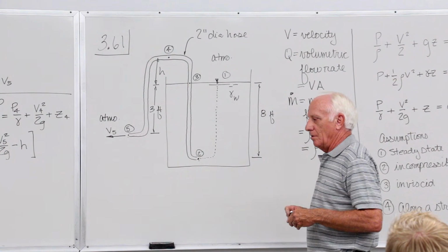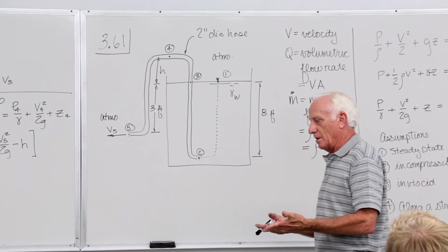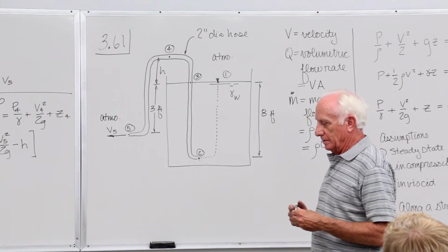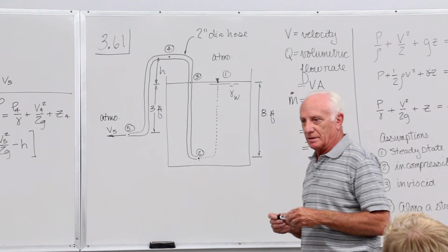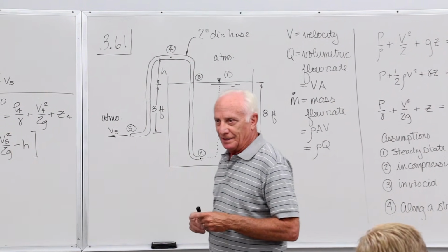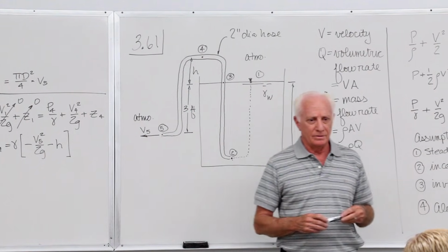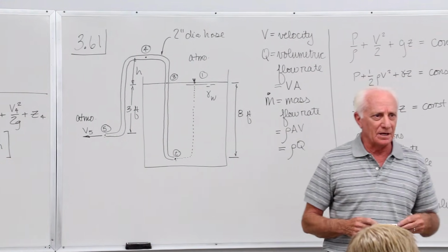So that's what happens. The pressure gets so low that the liquid water gets vapor bubbles in it, and then it won't work anymore. It's somewhat similar to your car's gasoline line. Ever hear about vapor lock? I thought gasoline's a liquid. Where'd the vapor come from in my gas line?